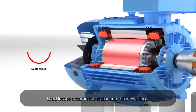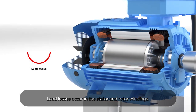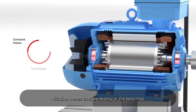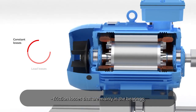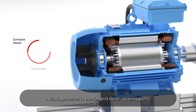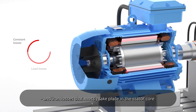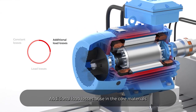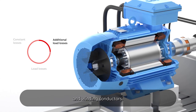Load losses occur in the stator and rotor windings. The so-called constant losses consist of friction losses that are mainly in the bearings, windage losses in the fan and other rotating parts, and iron losses that mostly take place in the stator core. Additional load losses arise in the core materials and winding conductors.